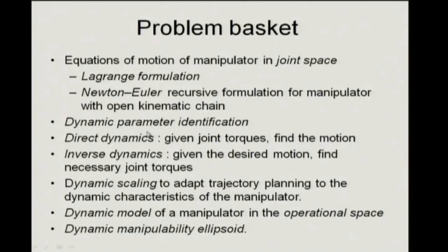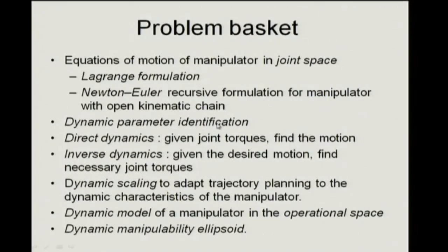So, in general this is difficult, identifying the dynamic parameters if you have to measure them. There is a method by which you can identify these various dynamic parameters. You may not have the CAD model, you may not know the densities, you may not know every part. Somebody will give you a CAD model but will not tell you where the screws are. So, you can go through a process of dynamic parameter identification, which is important to implement the control. So, that is one of the problems.